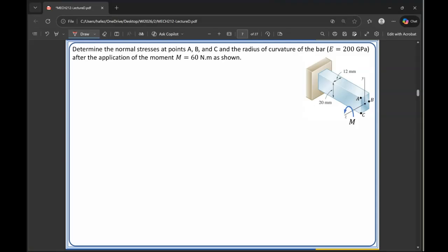So given all these examples, really we find bending to be ubiquitous. Remember, our goal is to be able to comment on mechanical safety of these components in those applications that we went over. So we have to be able to quantify stress. In bending, two stress types occur. One of them is normal, the other one is shear stress due to bending that we'll go over later.